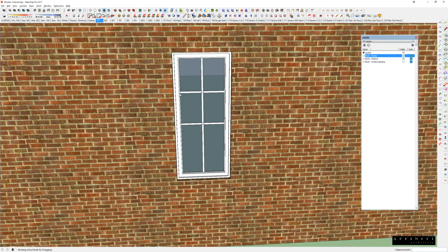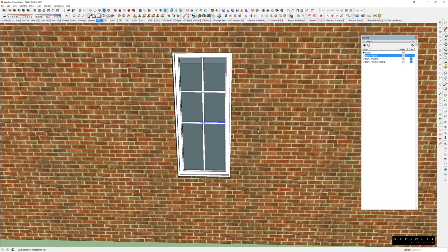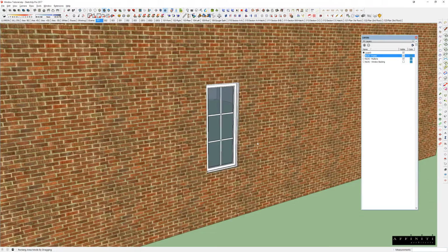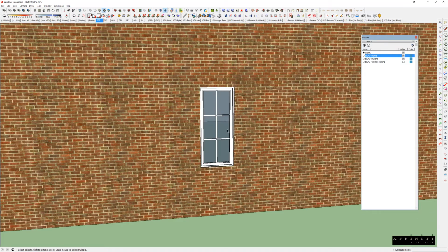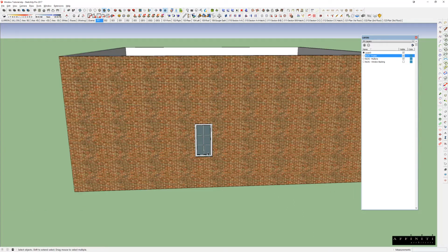Yeah, I need to come back in here and actually update my mullions, but I can actually still do this from the outside as well, and just respace these, knowing if I went 12, then this one's 8 and this one's 4, and it's still properly spaced. So just that easy, I just adjusted my window. I'm going to undo that.